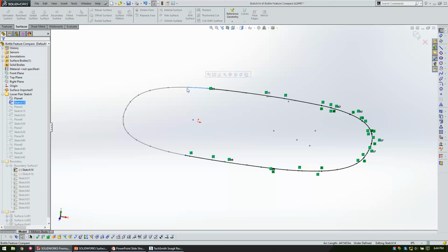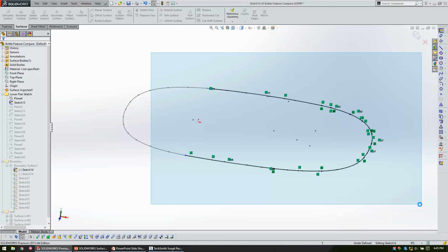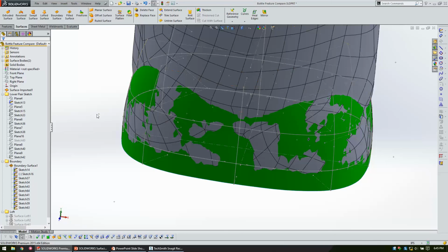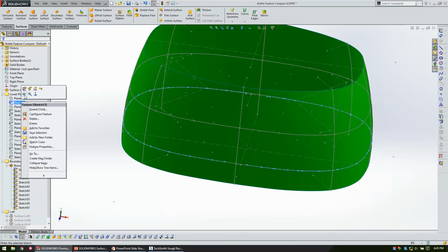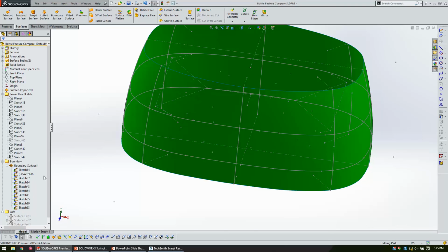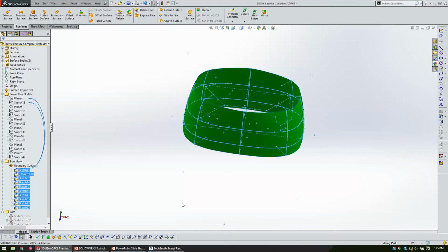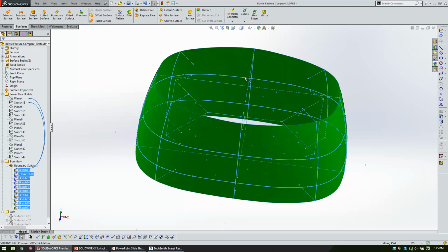So here's the original sketch that I converted off the scan data geometry. And then you overlay sketches on top of that, often splines or arcs and lines, avoid splines. And you just try to get it to close, and it depends on your tolerance and that kind of stuff. This can be a really easy job or a miserable job. But once you overlay that, then you can delete your source sketch, or hide your source sketch here. And you end up with good sketches like this, which is good human-laid manual geometry that's decent to work with.